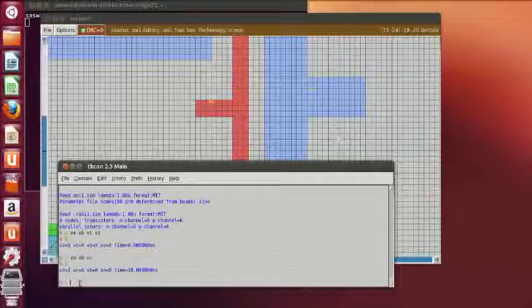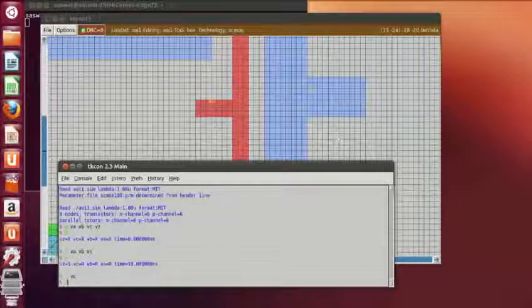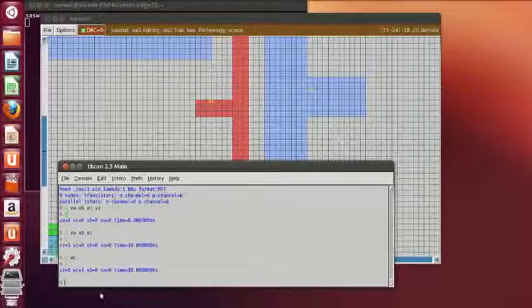Let me give high value to VC. So certainly we'll get the output as 0. Okay, why? This is 0 0 and output will be 0. This is 1, so OR output will be 1 and the invert will be 0 again.